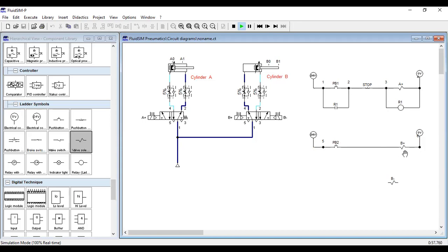So even if B plus is de-energized, the cylinder does not return. Meaning, in the case of the absence of power, so long as you have already energized B plus, the cylinder will remain in the extended position. Okay, so in the case of the single coil,